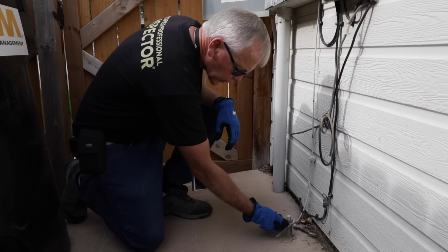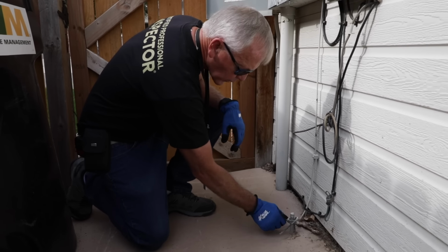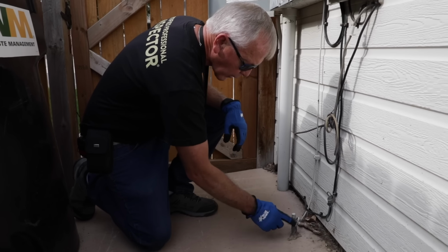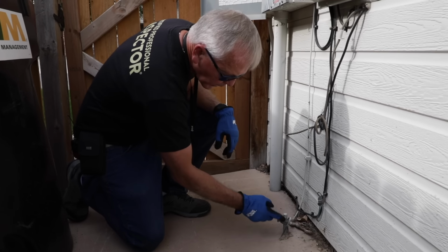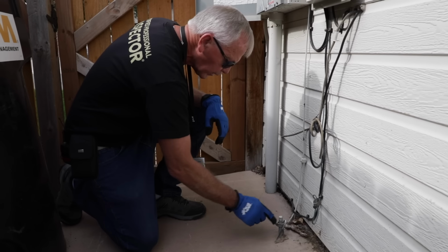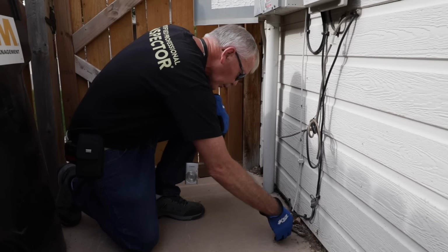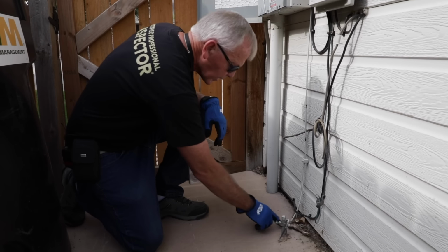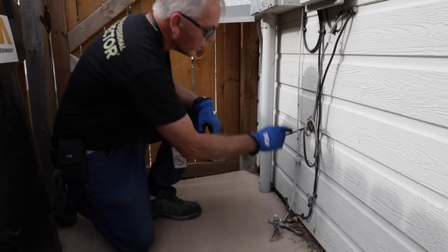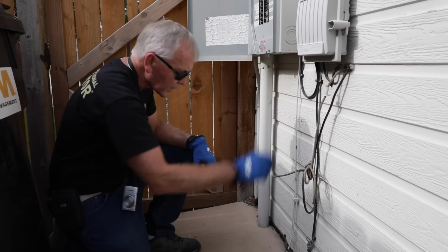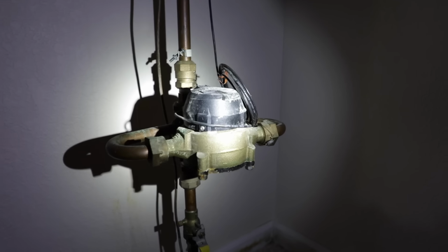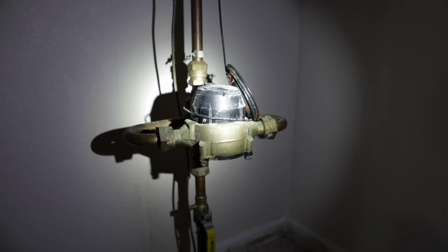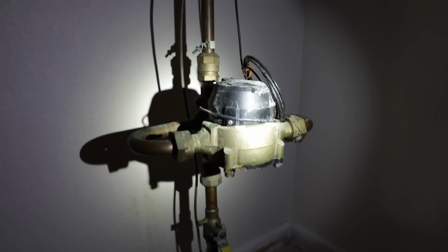So we're going to go down here and check the ground rod, part of the service grounding. And right away, I'm going to just make sure that these connectors are tight. Here's our grounding electrode wire. This is considered to be our grounding electrode. That's the ground rod. Everything looks to be tight and pretty clean. I can see that it comes up over here and goes directly into the service panel. So everything looks pretty good here. We're now going to move on to the water main and check that ground connection down there in the basement.